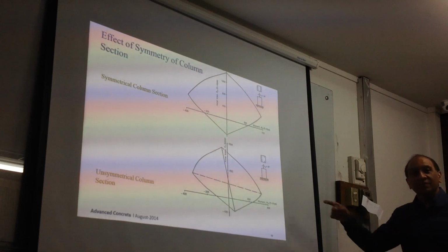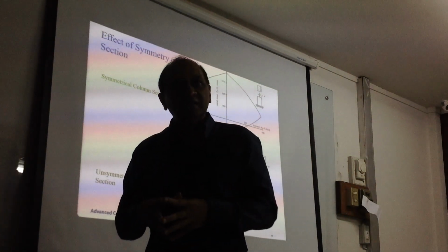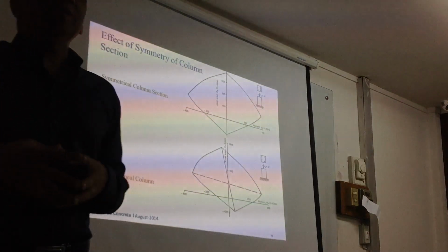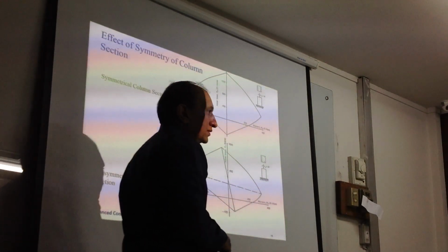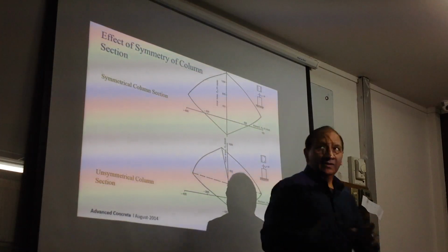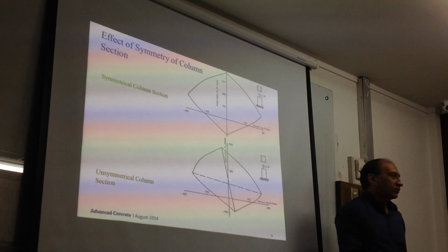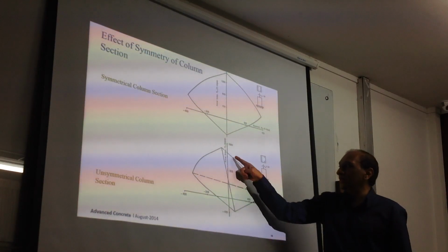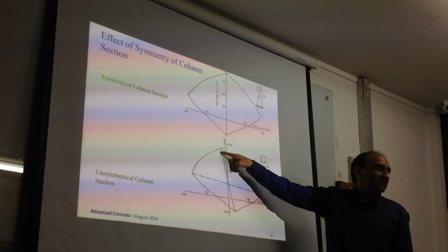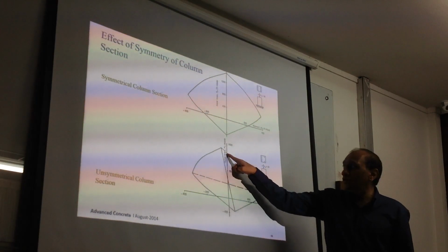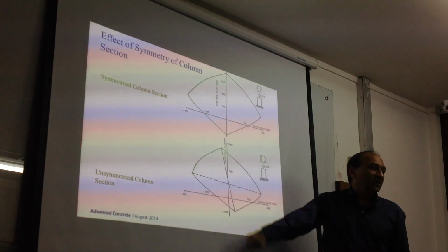So that is why unsymmetrical sections have this problem of these plastic centroid not matching with the geometric centroid and then creating this extra problem and shifting the entire interaction surface in a oblong manner. So now it is no longer the same. So now at this point you still have a moment, right? If you want that, you need to have a negative moment to go to that point. You cannot reach the next point anymore, right?